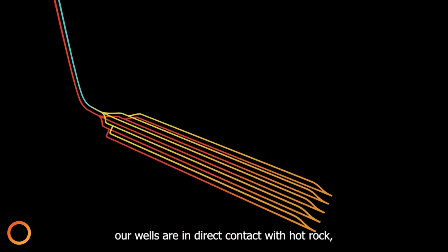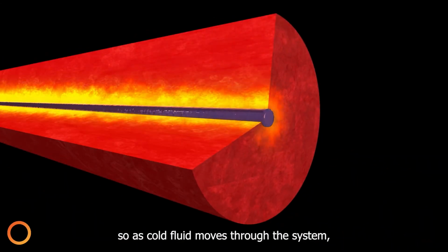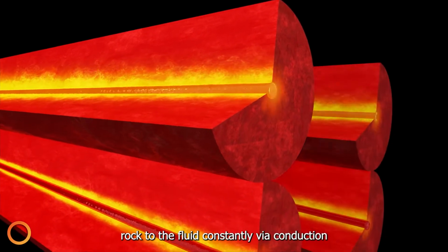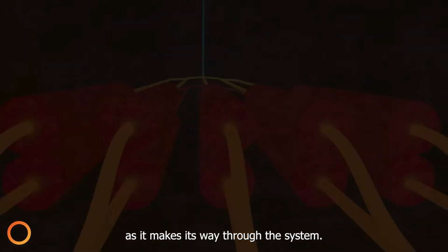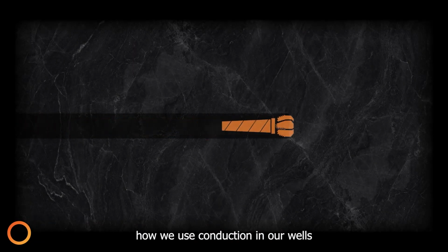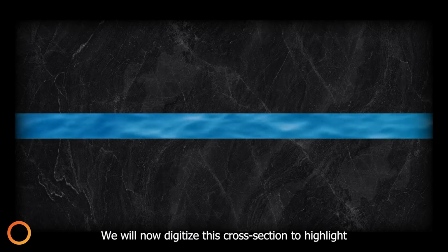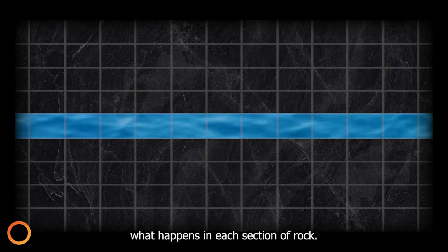In an Eavor-Loop, our wells are in direct contact with hot rock, so as cold fluid moves through the system, that direct contact transfers heat from the hot rock to the fluid constantly via conduction as it makes its way through the system. To represent how we use conduction in our wells to pull heat from the rock, we must imagine a cross-section of a well bore through the rock. We will now digitize this cross-section to highlight what happens in each section of rock.